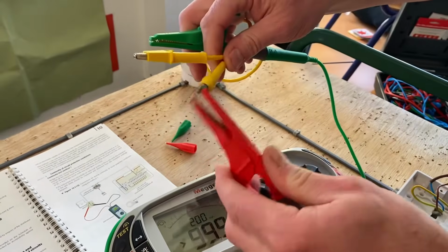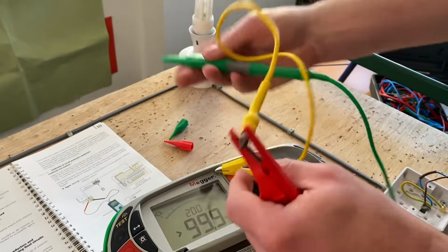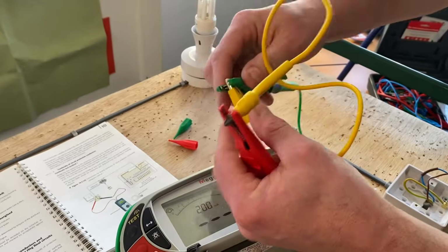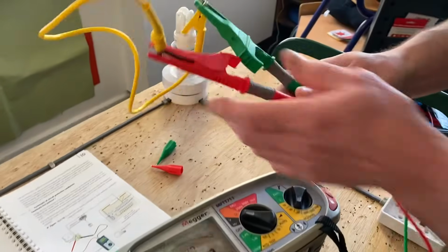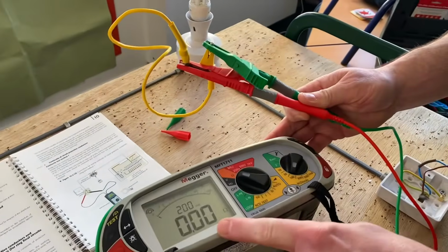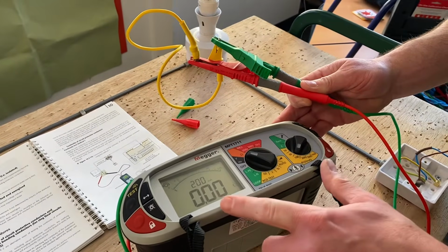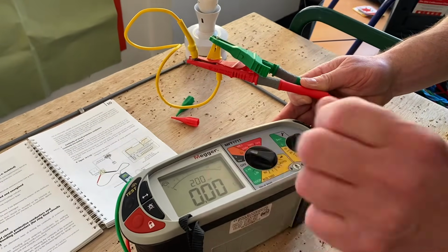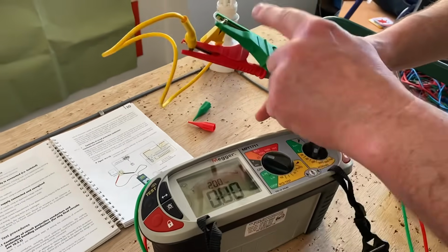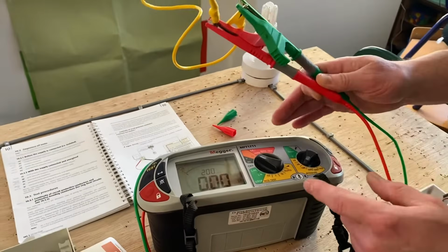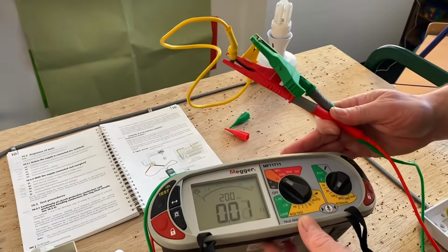So I'm going to link them together, crocodile clip on one and crocodile clip on the other. You see straight away, without even touching the machine, that we've now got a reading on it. It is saying 0, so that's a little bit of luck to start with. If it was flashing 0, we know it's below 0. So it's saying that we've removed the resistance of those leads. But let's show you how we would remove that resistance.